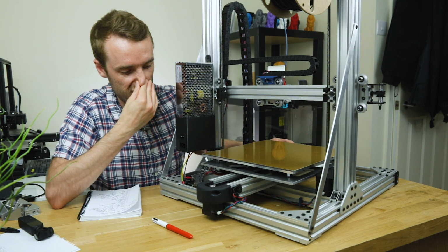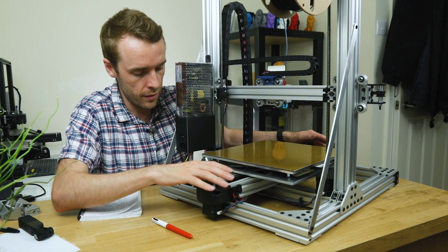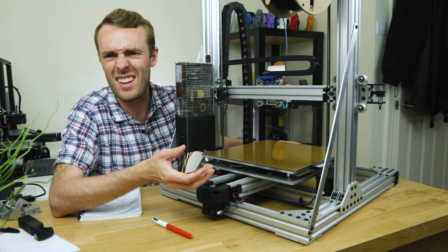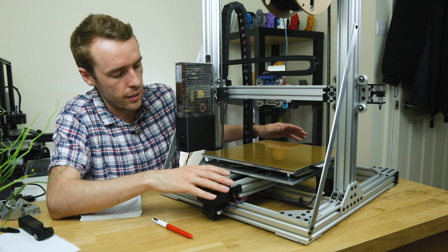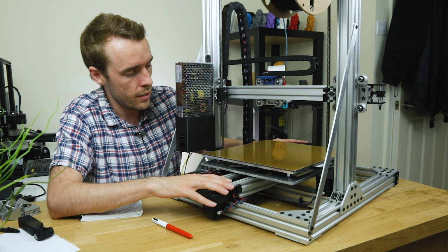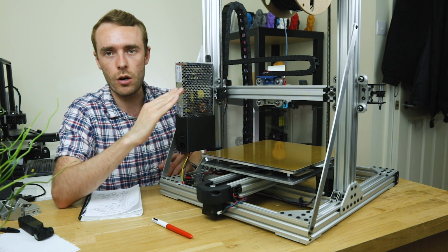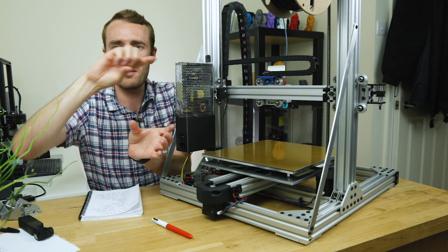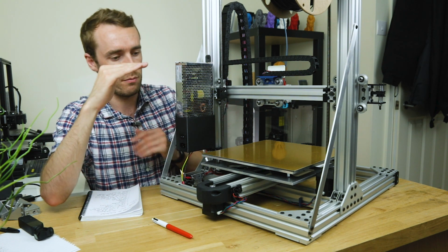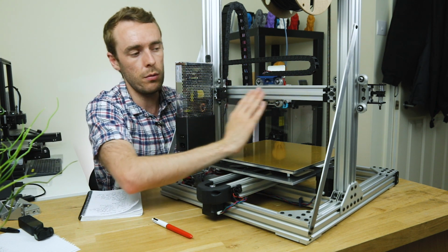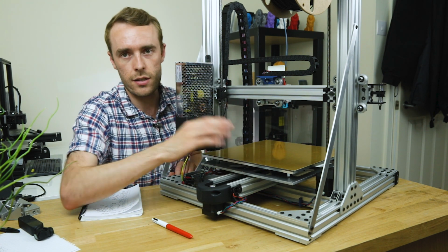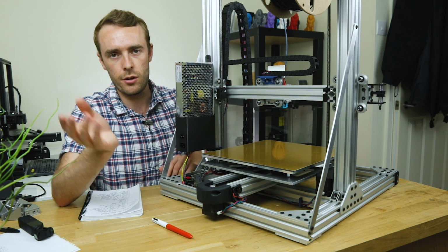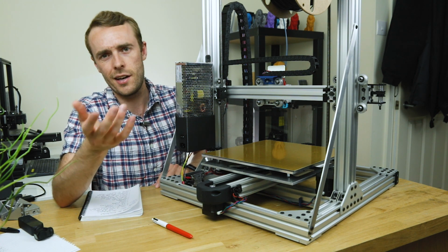While I do like the fact that it is mounted to a rail and it can come off and be changed fairly easily, I'm not going to demonstrate that now, but it does mean that the actual straightness is maybe questionable. The reason that matters is it can skew the whole print. So instead of printing a square when you're trying to, you end up with more of a parallelogram. Your top and bottom, where they get drawn by the x-axis, will be straight because that's straight. However, this axis could be skewed. So instead of moving straight along like that, you end up moving at an angle, drawing angled lines. So your 90 degrees is not 90 degrees, it can be like 89.